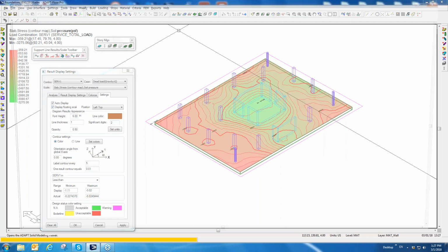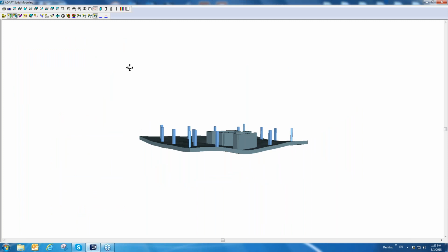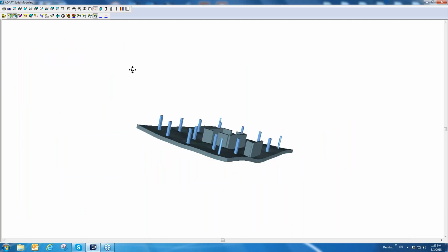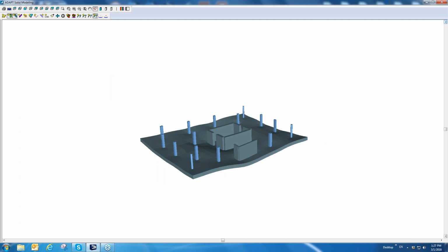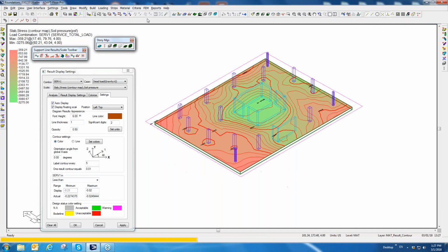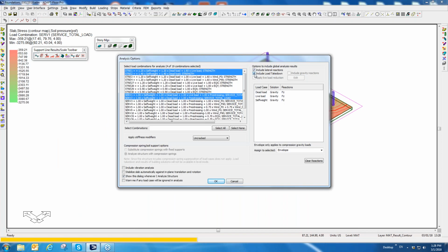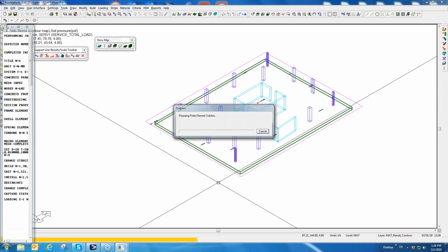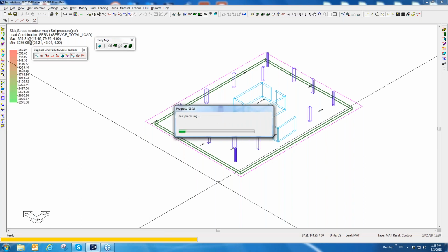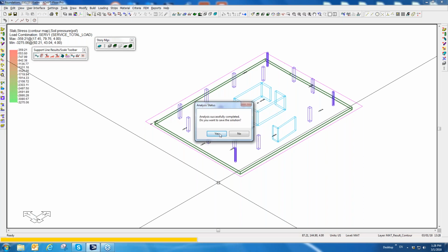And if we go in here to the model viewer, you can see that we get some deformed shape based on that applied load. Now, if you forget to actually include the reactions, that's something that also comes up quite often. If I go back to analyze and I forget to include the load takedown, it should be pretty clear that there's no reactions being applied, but sometimes people miss that. It's kind of over here to the right-hand side, and I rerun it now, and we're expecting to see some high displacements where we have this large core wall and maybe large point loads from columns.